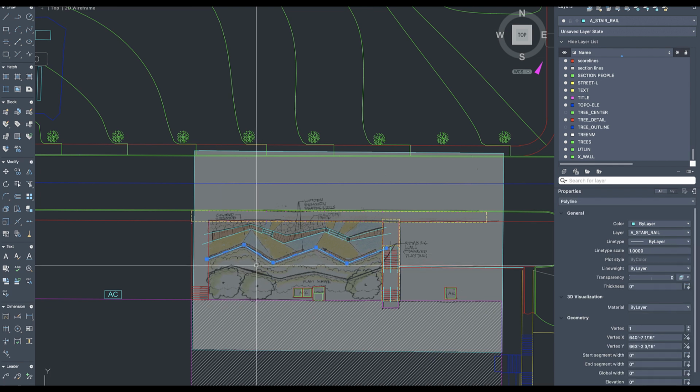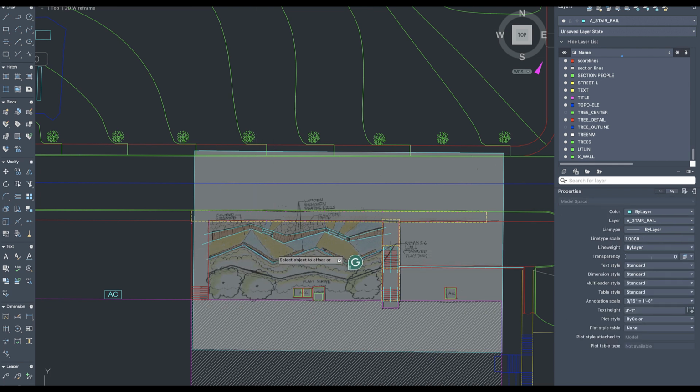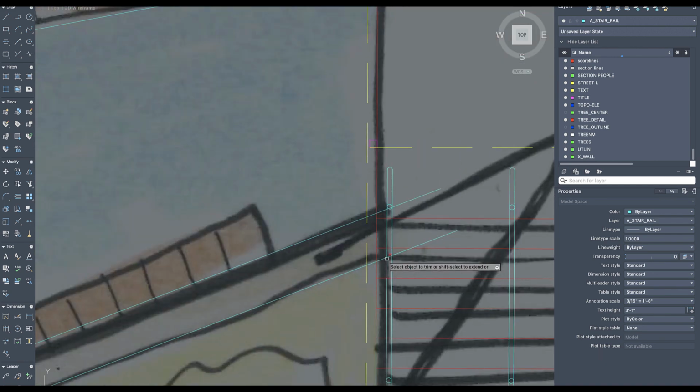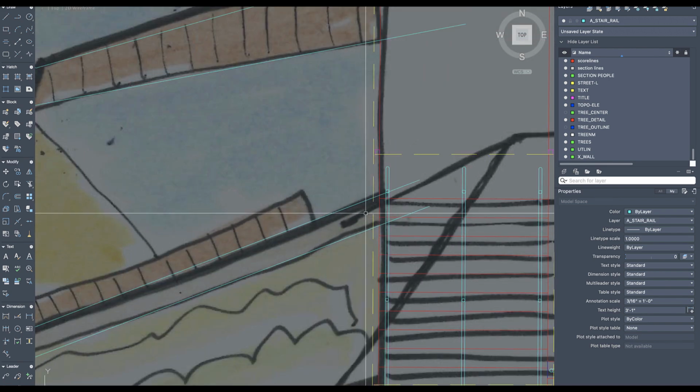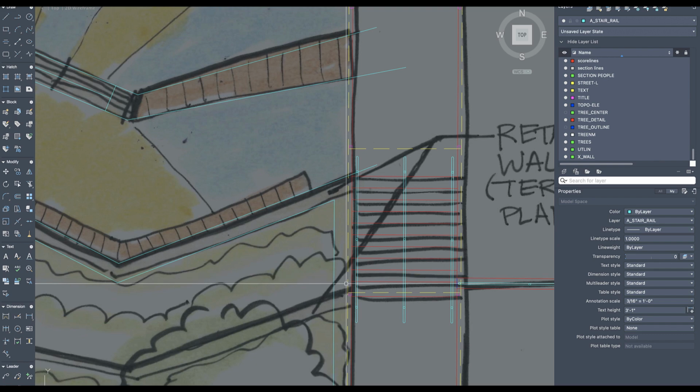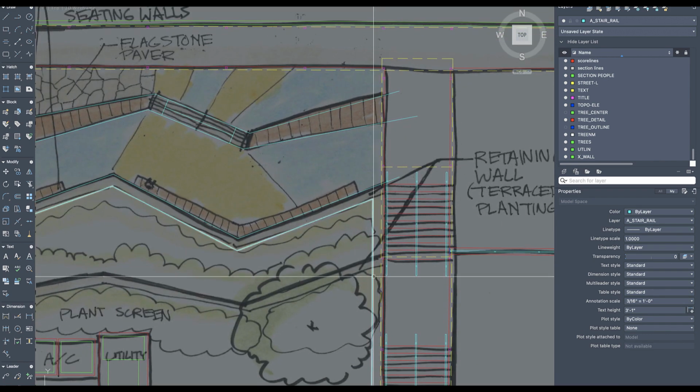And now when we click on that, we've got the entire thing. When we offset this, we do it one time, and we've got that entire piece right there set and ready to go. Now this wall is going to kick here. It's going to turn back this direction. So we're going to offset another 18 inches from this line, and then we're kind of back to figuring out fillet, radius 0, and clicking that line. We know that wall is probably going to kick back and potentially even die into this last wall right here.